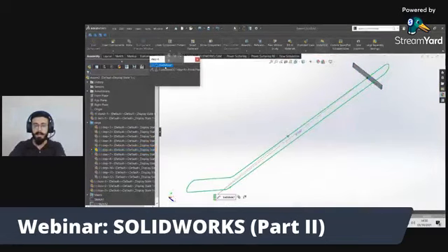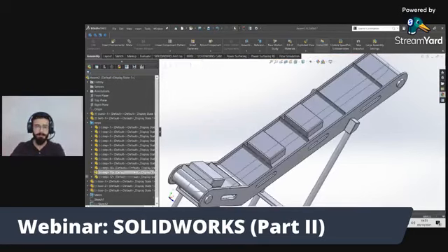I added a path mate. What is the path mate? You give a path to your body, through which it will move. It is bounded to that path. Your body cannot make other movements except moving around the path. This is the path mate used here.